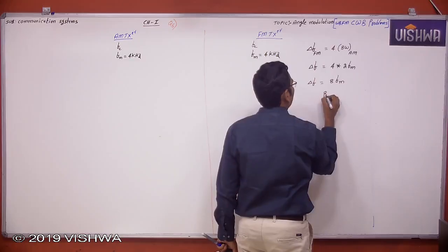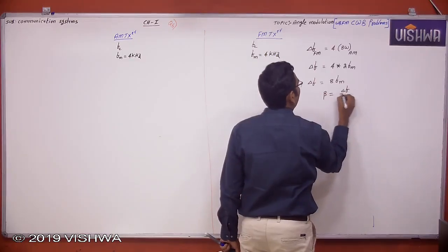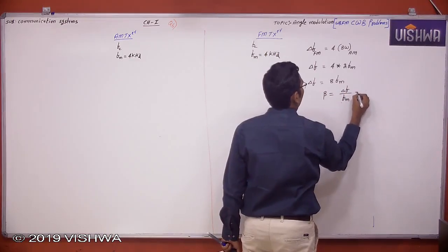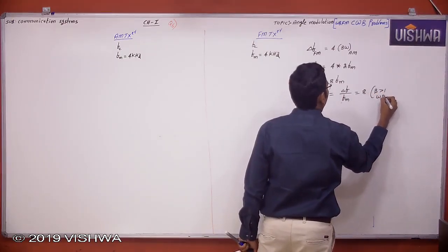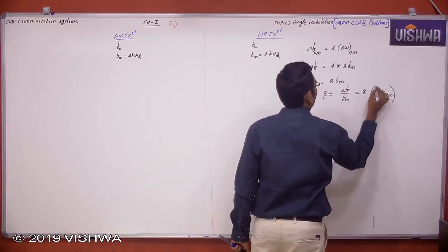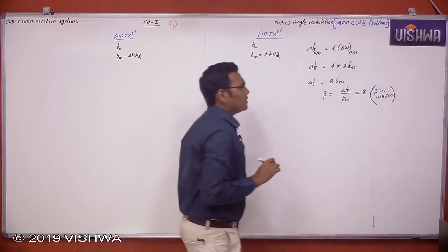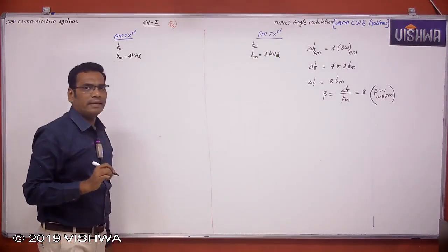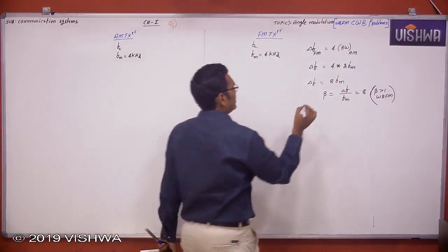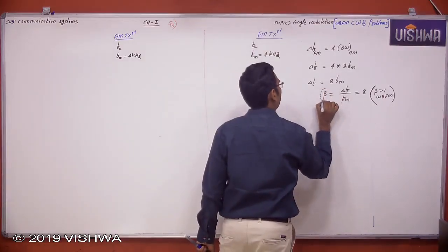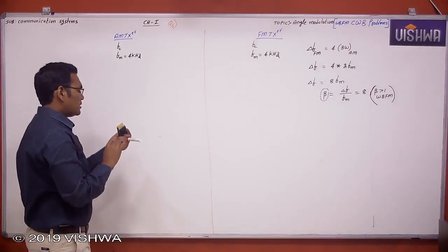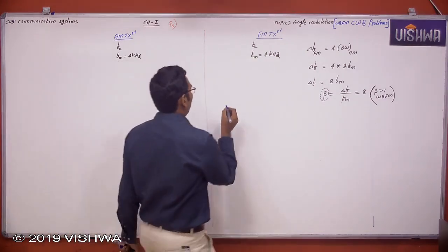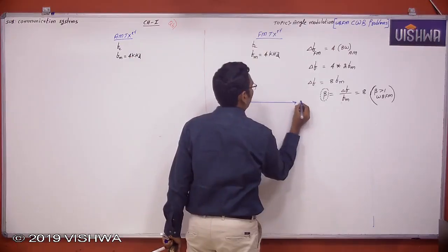So the modulation index β is equal to delta f by fm, which is equal to 8, which is greater than 1, wideband FM. He is asking what the modulation index in FM is; the answer is completed. Another question asks for the spectral amplitude of fc plus 4 kilohertz.